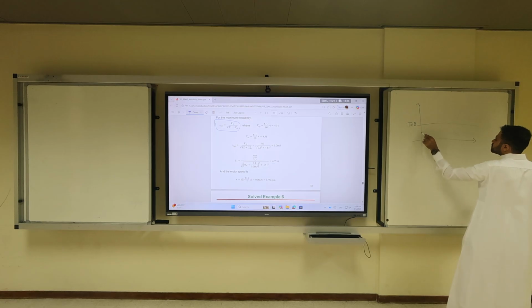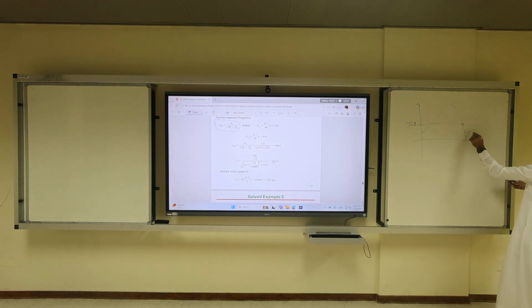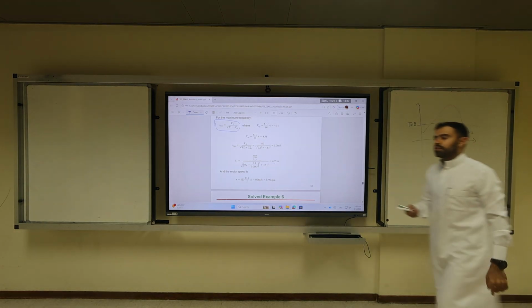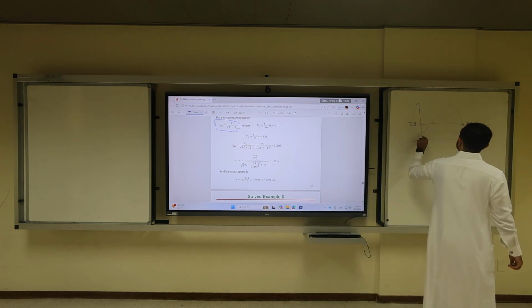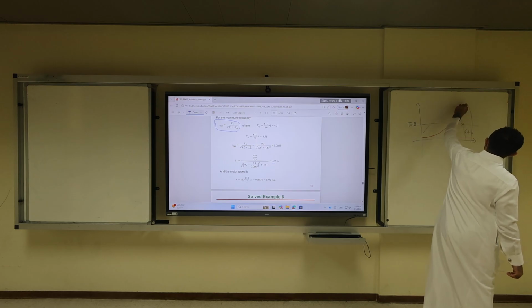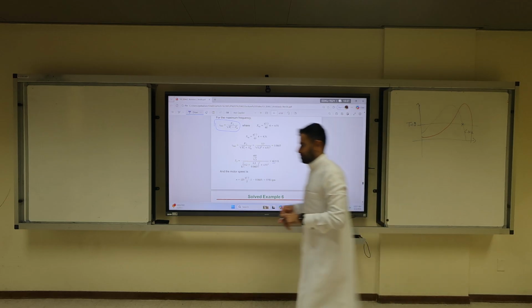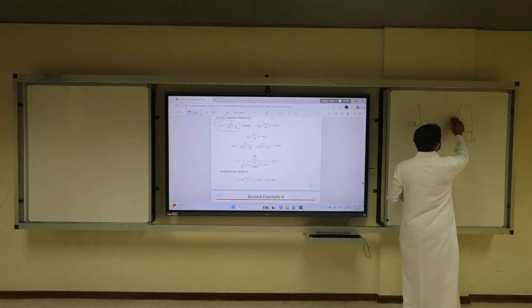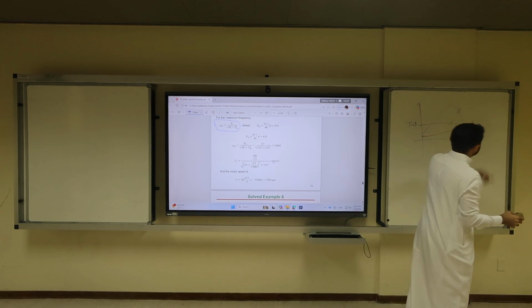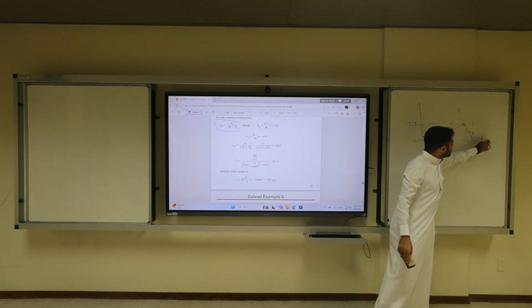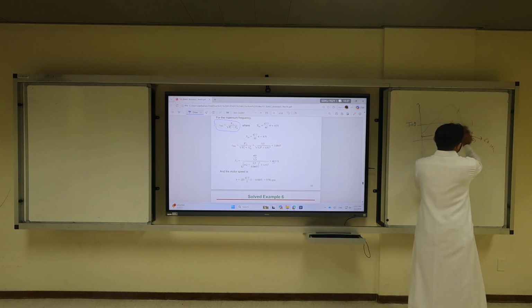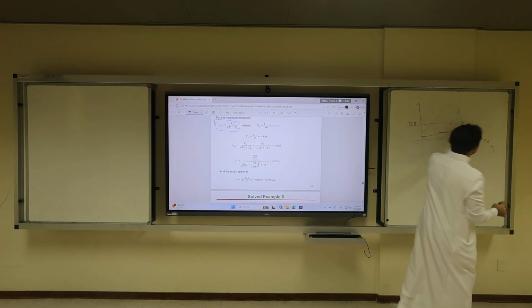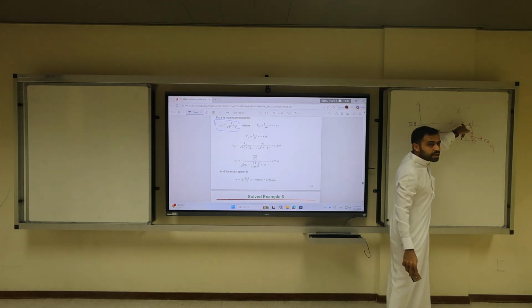For the 60 Hz curve, you're operating at this slip. So this is 60 Hz. For the 67 Hz, no, my bad, it's wrong here. For the 67 Hz, you're operating at this curve. Clearly? You see it now? This is the 67. I'm exaggerating, but the slip is here. So you see the two different points. Here we're operating at the peak, here we're operating at the linear region.